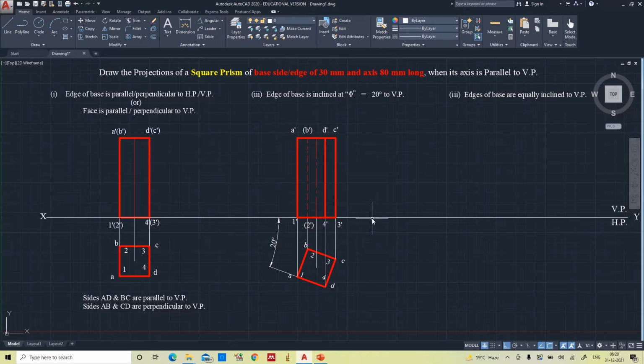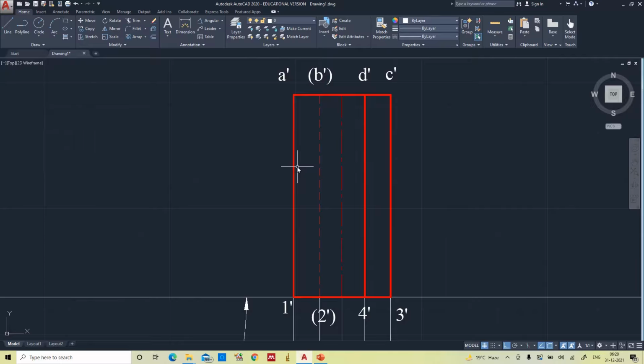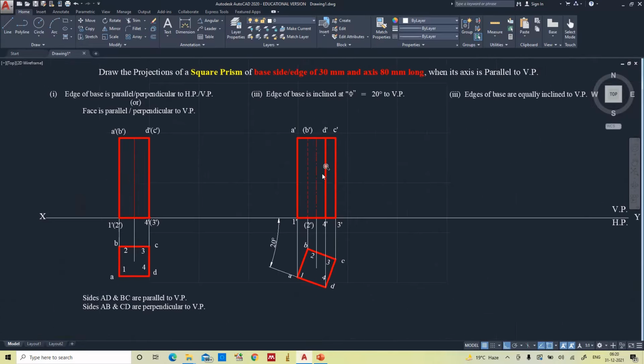So if you want to make some more, see, LTS is already 1, so you can apply 0.5. Yeah, see, the lines get reduced. Perfect, still more perfect representation. Yeah, okay, so this is also a center line. I will apply center 2.